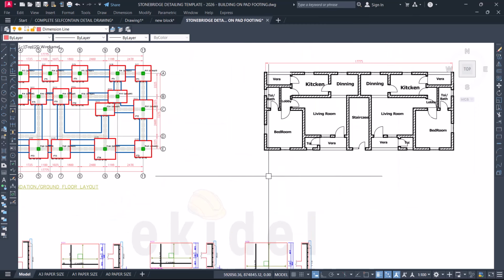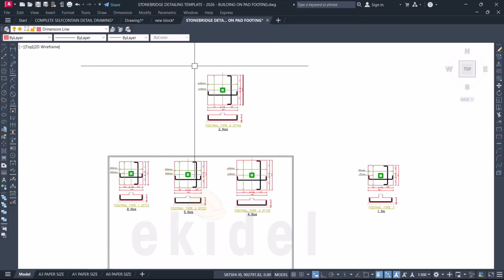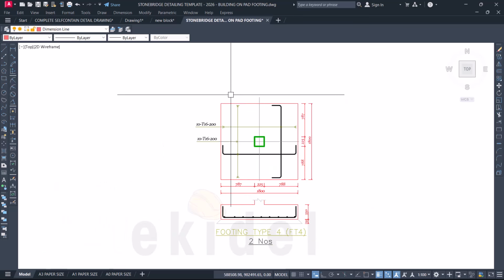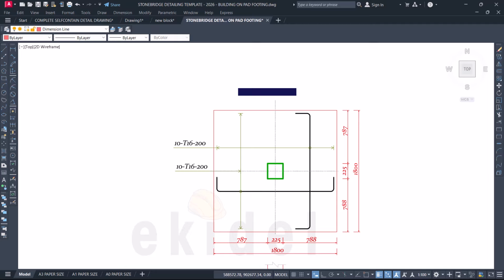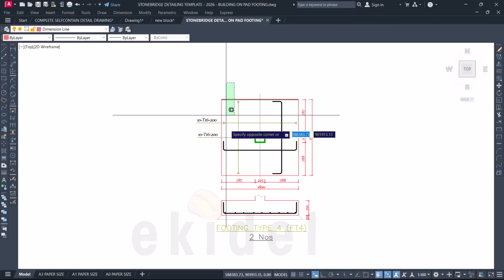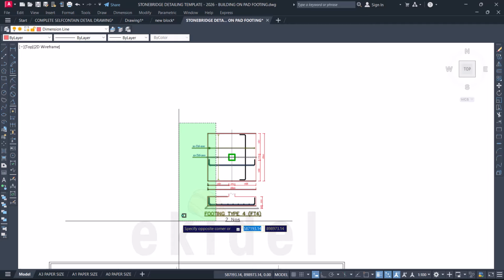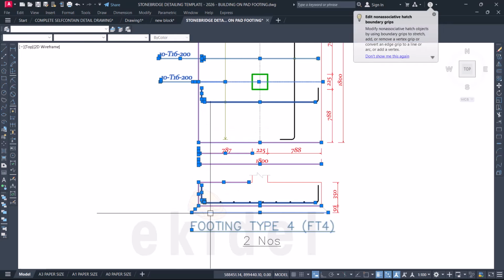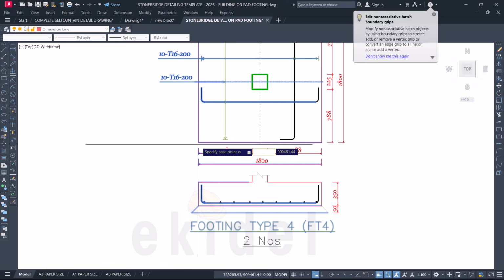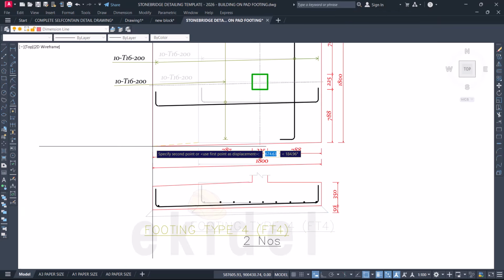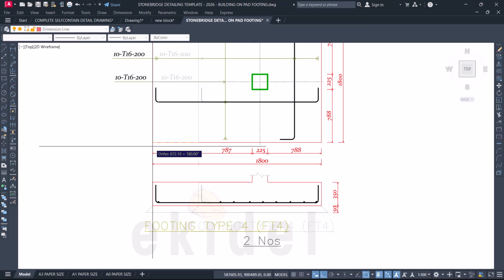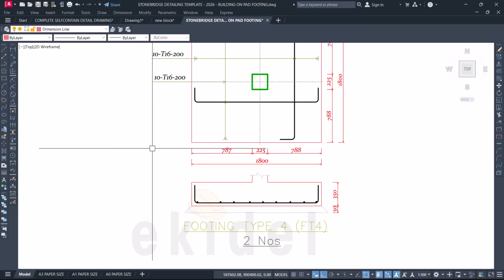Then we then come now, modify this footing to fit in what we have. So we then come down, click on this. Now since it's 1 by 1.8 and we want to achieve 2 meter by, what? 2 meter, we need to offset 100. Okay, 100. So we come now and then not offset, stretch on my snap, stretch it from here. Make sure you're on your auto to keep the line straight. 100 here, that gives us 19.